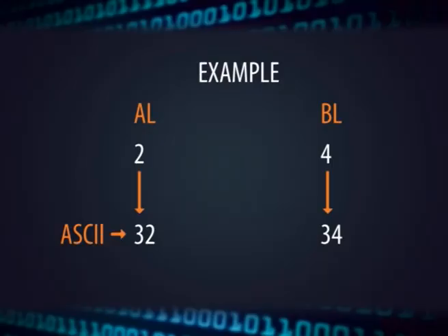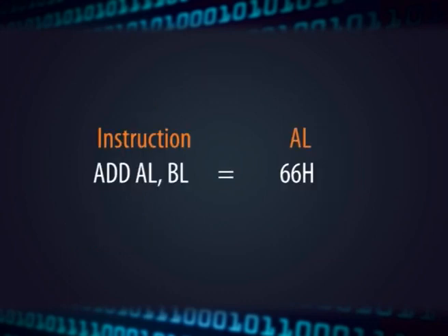The instruction operates and adjusts only on the register AL, and therefore it is mandatory that the result must be brought into the register AL. Assume you have to add two digits 2 and 4 stored in registers AL and BL in ASCII format as 32 and 34. First an operation ADD AL, BL is performed.